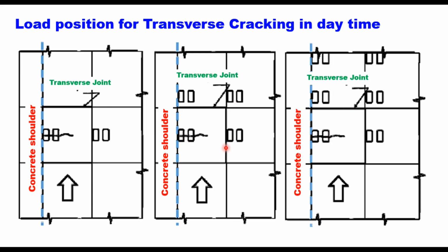Here first and last axle of tandem or first and last axle of tridem units are placed one after the other in the middle portion of the slab, and therefore these two categories of the wheels or axles must be considered twice.